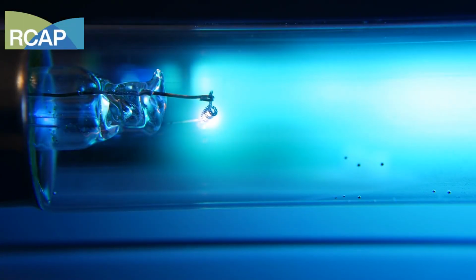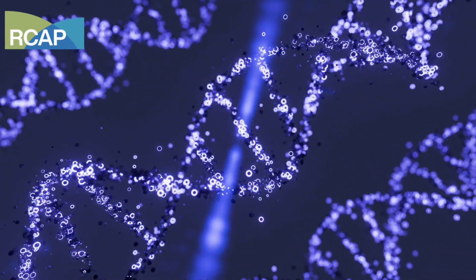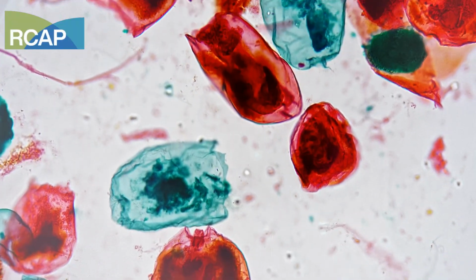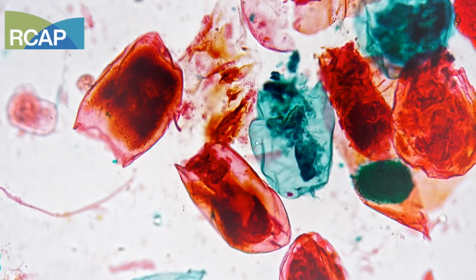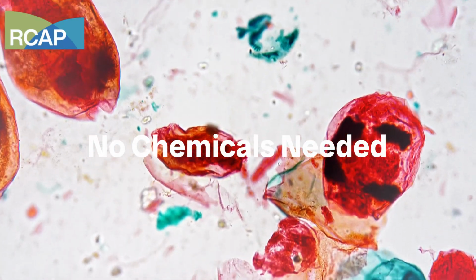Next, we will look at a potential disinfection process known as ultraviolet disinfection. Ultraviolet, or UV disinfection, uses light to scramble the DNA of microorganisms, making them unable to reproduce. It's very effective against bacteria, viruses, and even parasites like Cryptosporidium, and it doesn't add chemicals to the water.